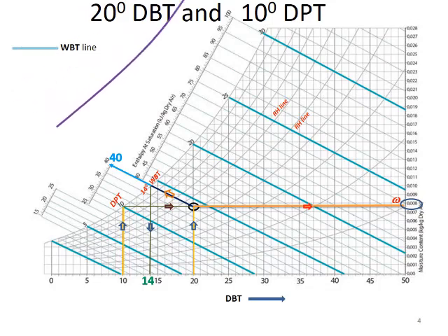Now, the relative humidity, so this line, again it is between 50 and 60, but almost midway, but not exactly midway, slightly below that, so you can approximately take it as 54%, okay? So this is how you have to find the other property values by locating a point on the psychrometric chart by using the given condition.